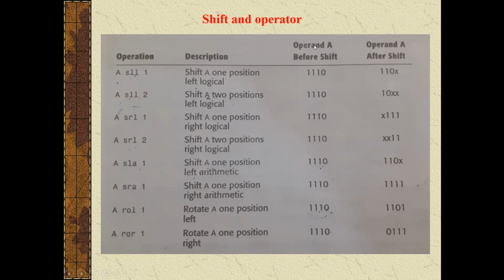If the data A contains 1110 and I want to perform a 1 bit shift, then I should write A SLL 1, which is shift A 1 position left logic. Such a command should be used in the programming.